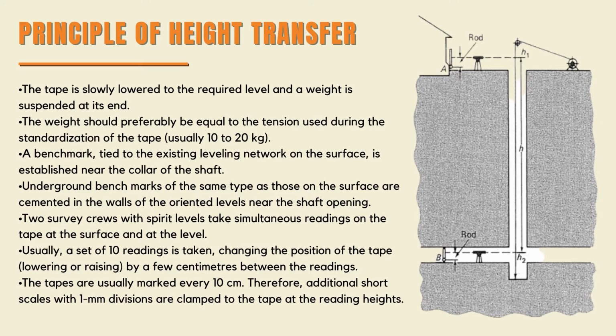Underground benchmarks of the same type as those on the surface are cemented in the walls of the oriented levels near the shaft opening. Two survey crews with spirit levels take simultaneous readings on the tape at the surface and at the end of the level.